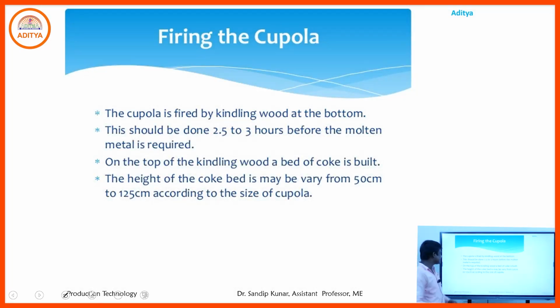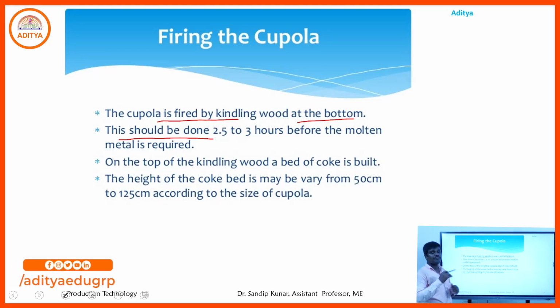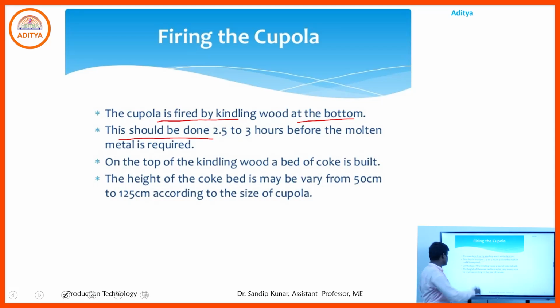Firing the cupola: the cupola is fired by kindling wood at the bottom. Some wood is used for burning at the bottom of the cupola. This should be done for 2.5 to 3 hours before the molten metal is required, meaning 2 hours 30 minutes to 3 hours.